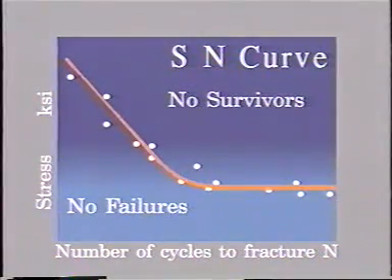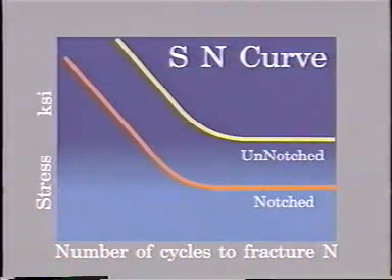A typical S-N curve for AISI 2340 steel shows that the number of cycles the metal can endure before failure increases with decreasing stress. The two curves for AISI 2340 steel are typical for steel. The steel is subjected to constant amplitude cyclic stresses, appearing as a fairly straight sloping portion at the low cycle section of the S-N curve, then straightening into a horizontal line at higher cycles.